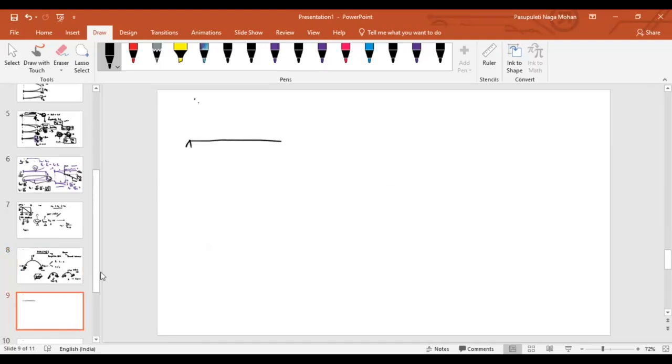Now, the general representation of why arches are important. If you consider any section here, what is the bending moment? Let the UDL be W, total length L. Let us consider this section at a distance of X. What about the bending moment at that section? What about the support reactions we know? WL/2. And the support reaction here is also WL/2.